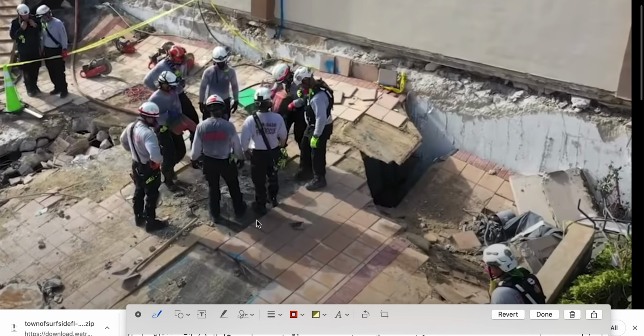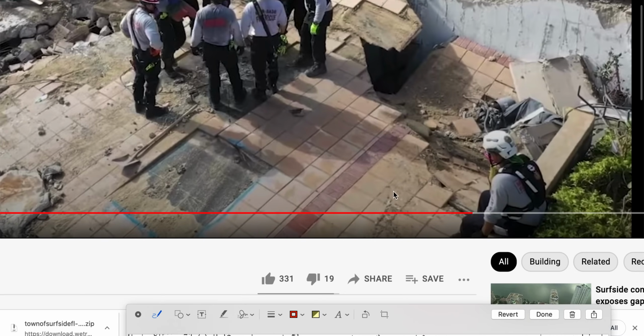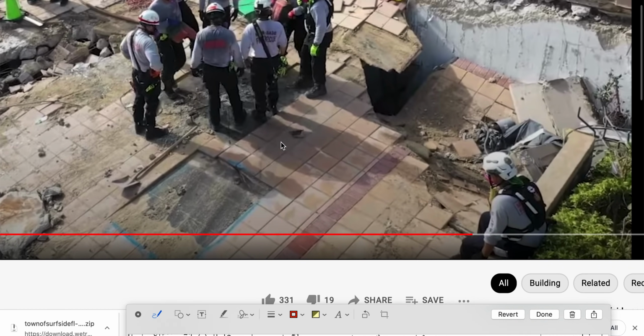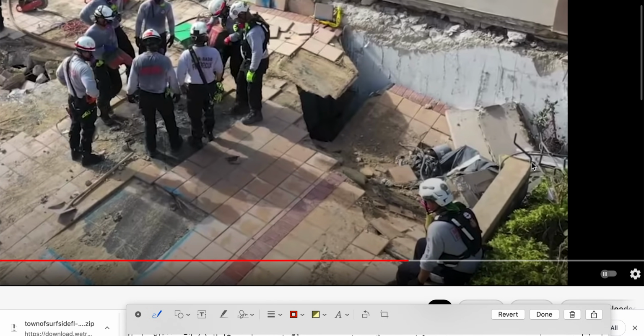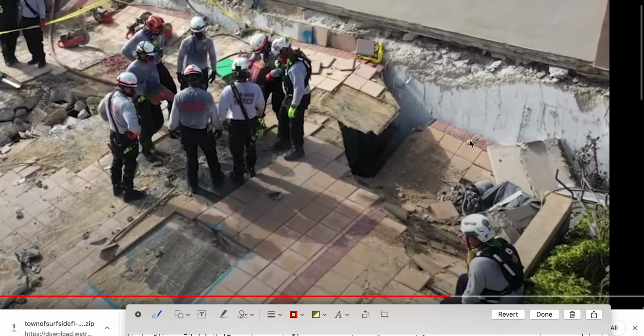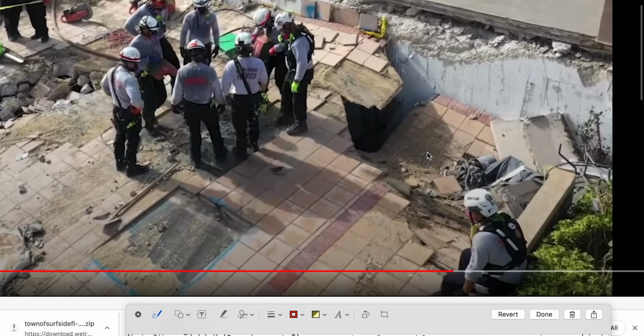I just want to show you that one didn't fully punch through. It landed there. You can start getting the wave effect. That looks like rebar right there from the end of this wall. It might have been anchored into the wall system. Incidentally, all the rebar that I saw looks slightly scaled, if anything, slightly rusted, and it's looking great. It doesn't look like it's swelling and all that other stuff.